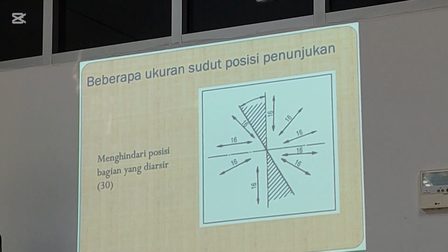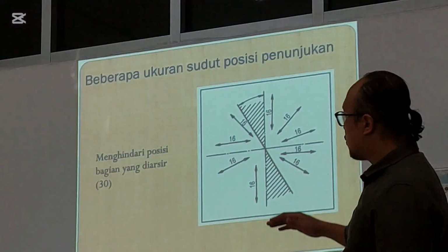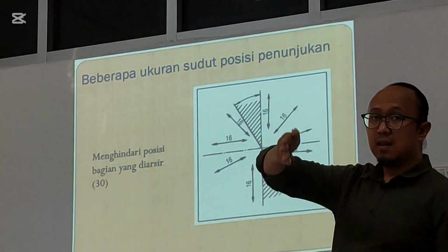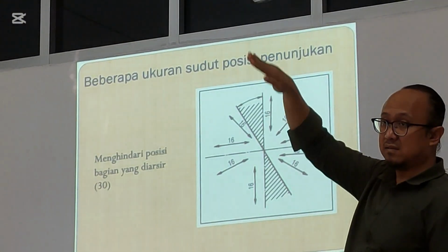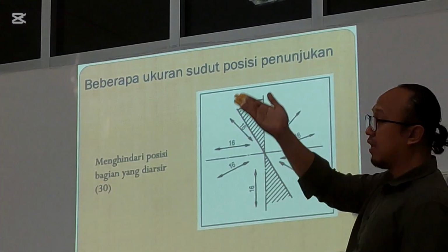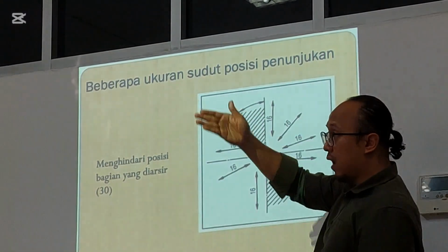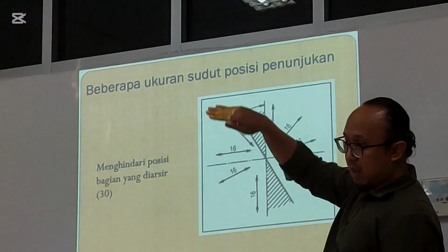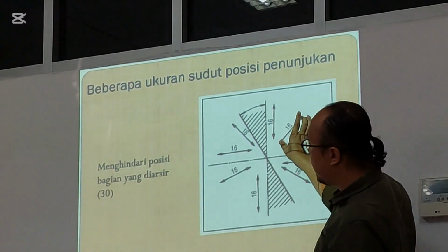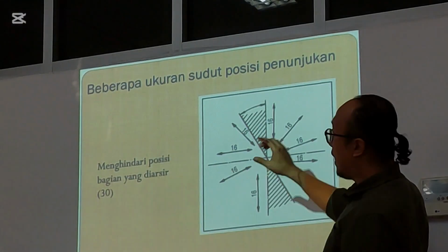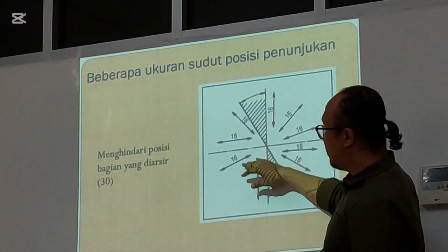And for the dimension, if your drawing is not horizontal and vertical, sometimes you need an angle for your dimension line. Because maybe the drawing has some area with a slope or angled side, so you must give the angled side line. So you can also use the same type.